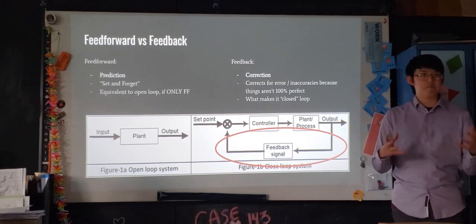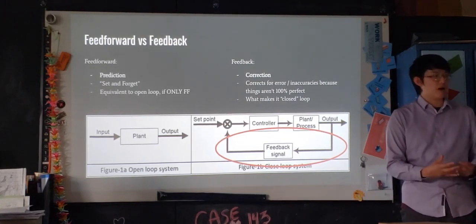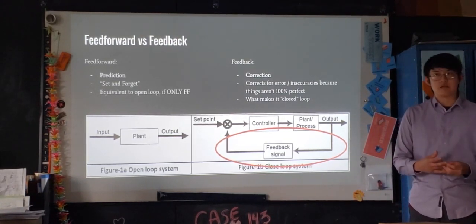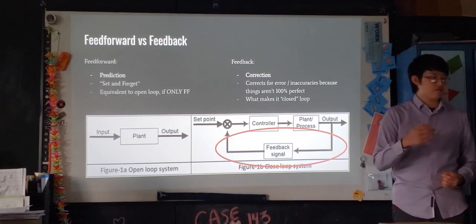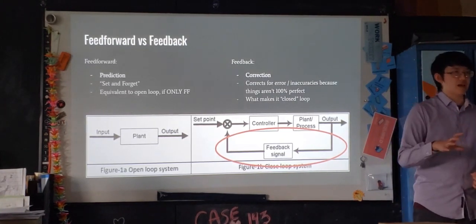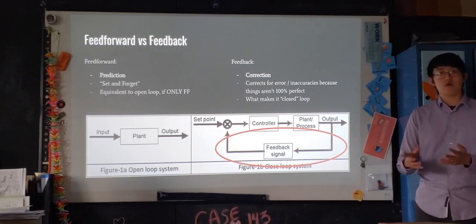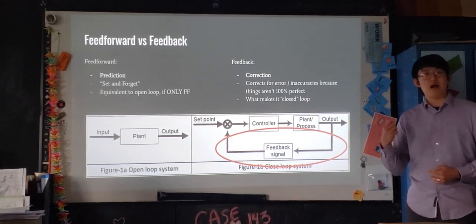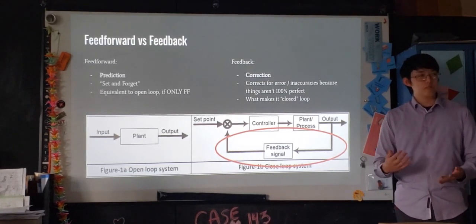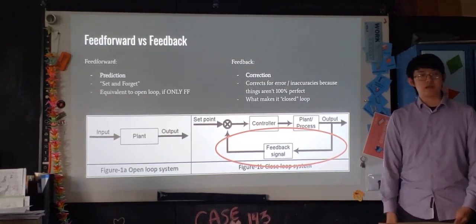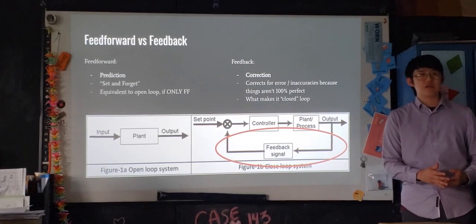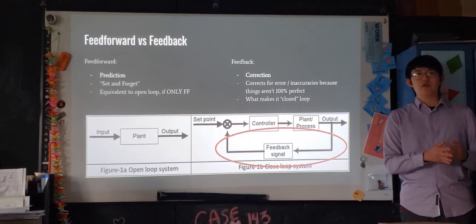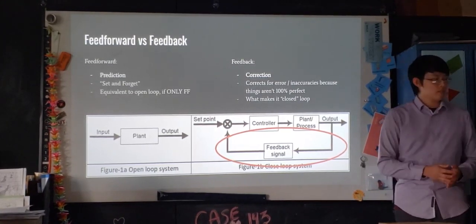Feed forward essentially embodies what you know about the motor. And if you give the feed forward an input of the goal, the set point that you want to reach, like 5 meters per second, feed forward will output you a voltage, the voltage to apply to the motor, because it does some math inside, because this feed forward knows a little bit about your robot.